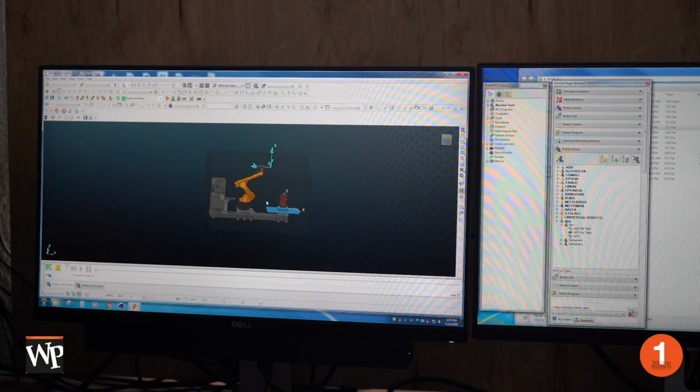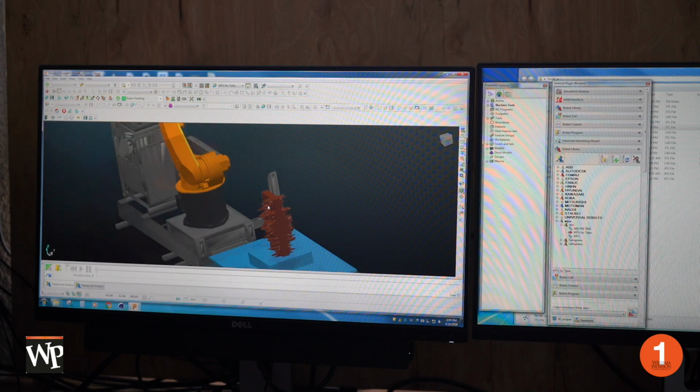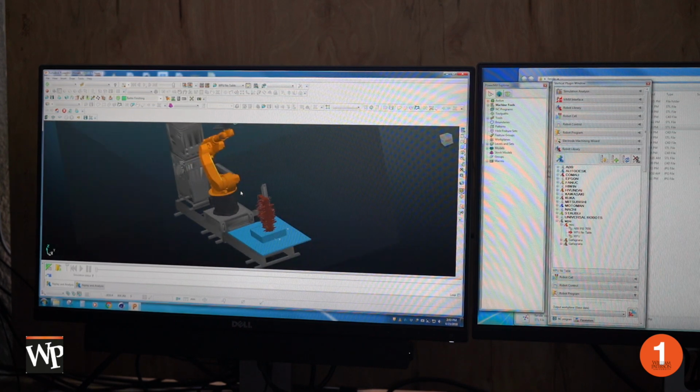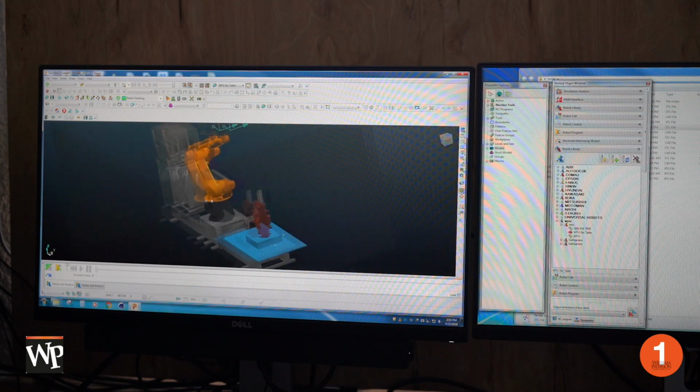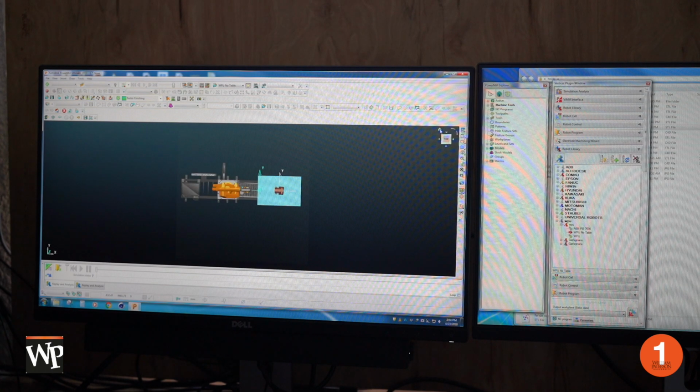in our Explorer here, we click and hold the mouse wheel to rotate around. We can zoom in and out by scrolling the mouse wheel. We can pan by holding shift and using the mouse wheel button. We also have a home button, which takes us to the top view.